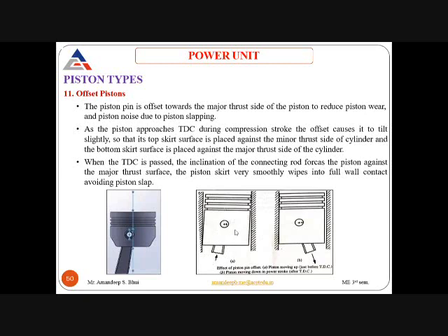Now what happens is the piston becomes tilted. So the top of the piston touches the minor thrust side, and the bottom left corner of the skirt touches the major thrust side. Now during the minor thrust side, because the thrust is minor, smaller, the wear is small. Okay, but during the